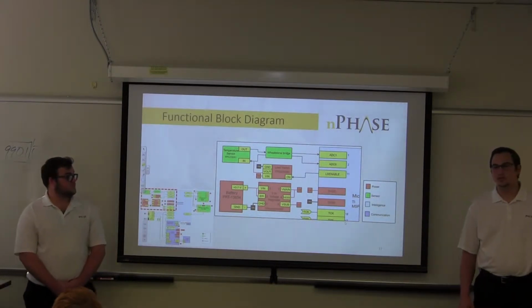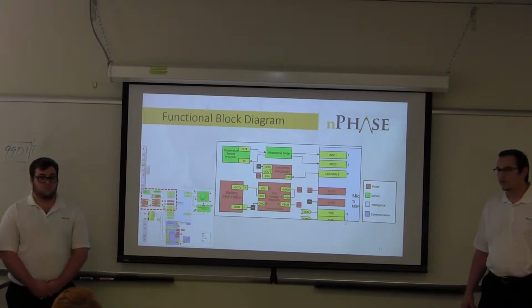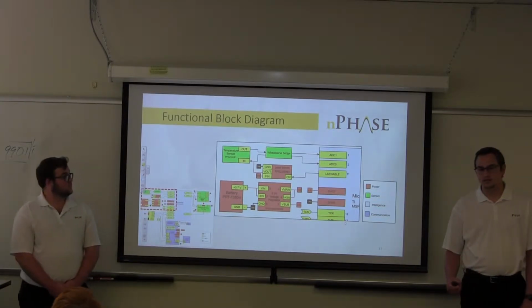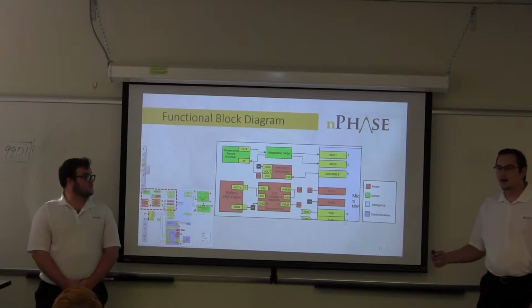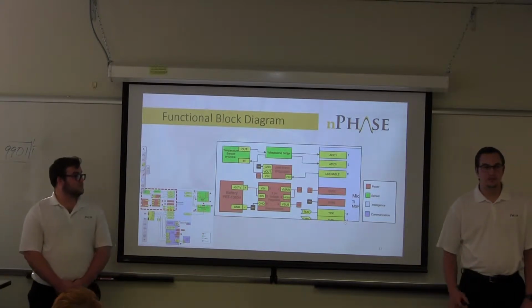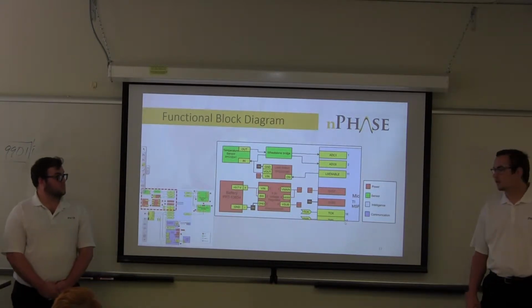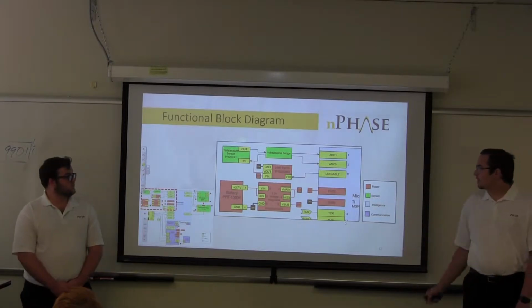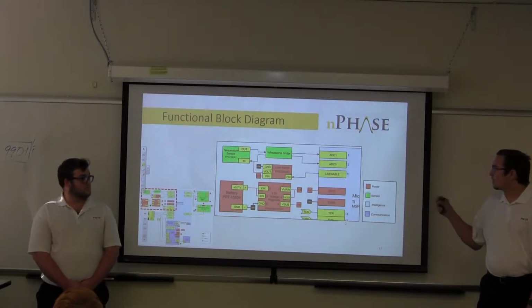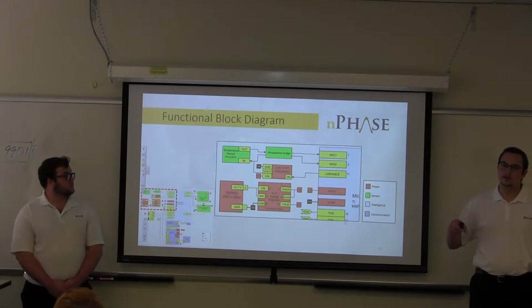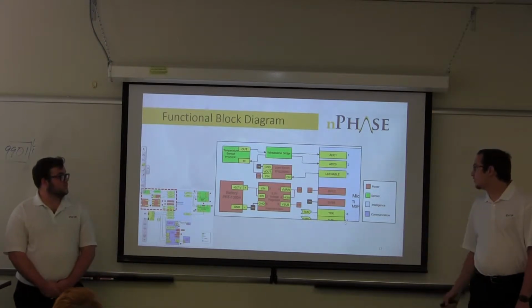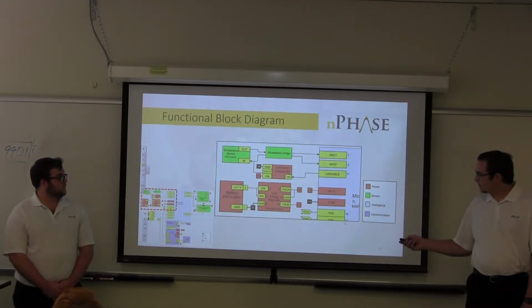The load switch is so we can turn off the Wheatstone bridge, which is used to get accurate temperature readings from our analog temperature sensor. We want to be able to turn that off and on because the Wheatstone bridge takes up a lot of power, and we want to be able to reach the 1 month. And we're getting those readings by measuring ADCs across the Wheatstone bridge using 2 ADC pins on our MSP430.